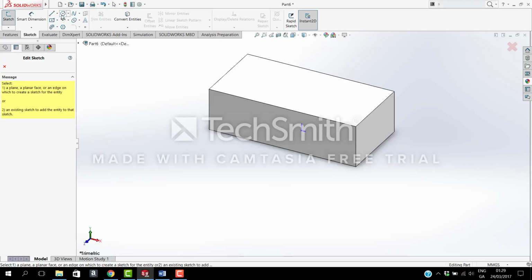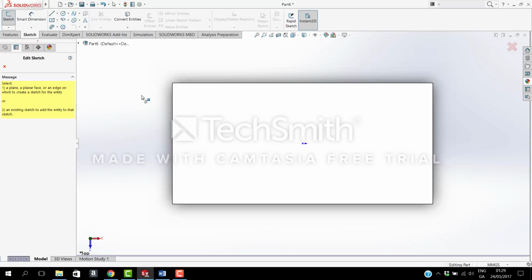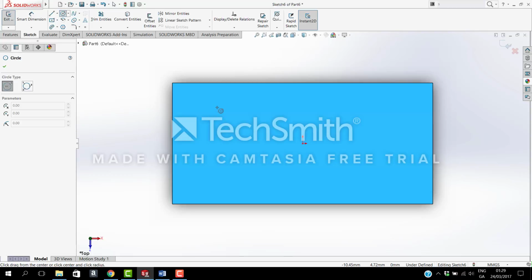on the top face. In order to become normal with the top face, this time around, I can hold down my right click and drag the mouse upwards. This will bring me directly to the top view. Now I must select which planar surface I'm going to do my sketch on. So I'll just click on this surface. This opens the sketch command.